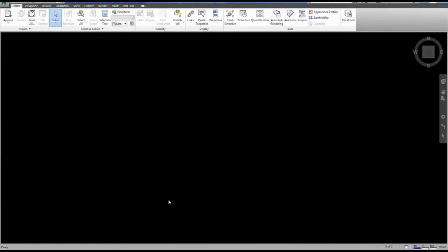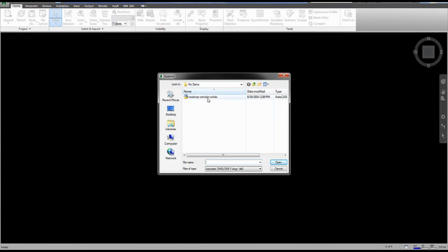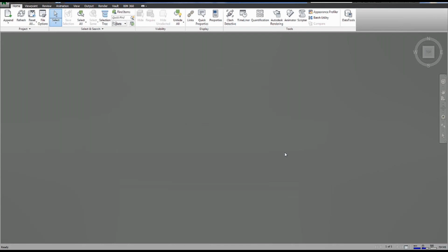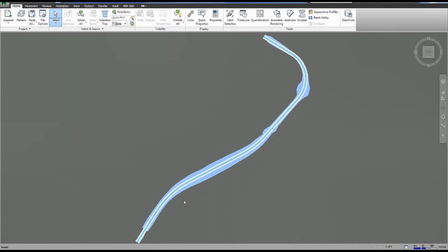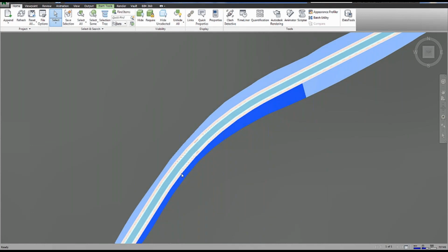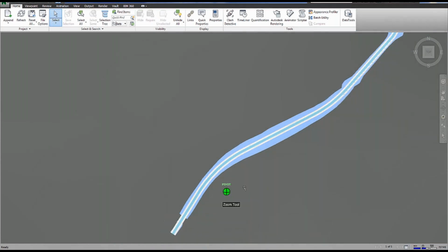First we're going to import this into Navisworks. If you haven't seen Navisworks, this is literally how the interface looks. We're going to import or append the solids that we already extracted. If you import it and you don't see it, just use zoom extents to zoom all. It is there, and here we are. The same thing that we've seen: the components are still singular, so you can select each and every component individually.